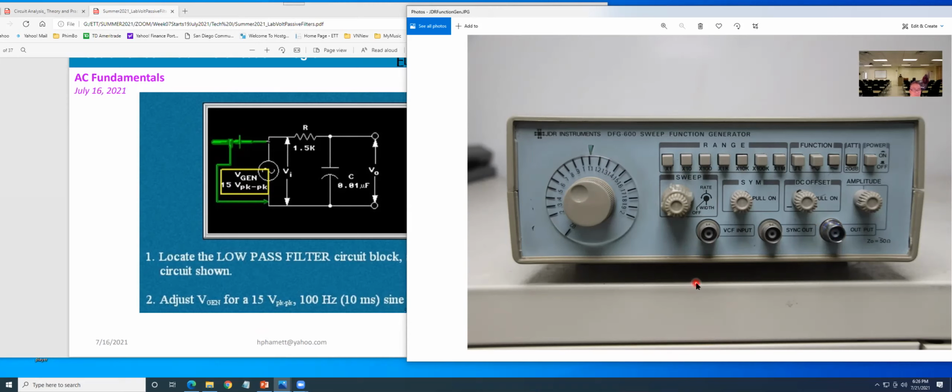Yeah. So for the range, you push times 10. The range will be 1K. That's okay. Times 10. So the second button, yeah. That means you can have 1K, you still get up to here. Okay, that's just a range. So pretty accurately, you put 200, that'd be fine. Then you turn the dial to 1.5, right here, right? Yeah, 1.5.